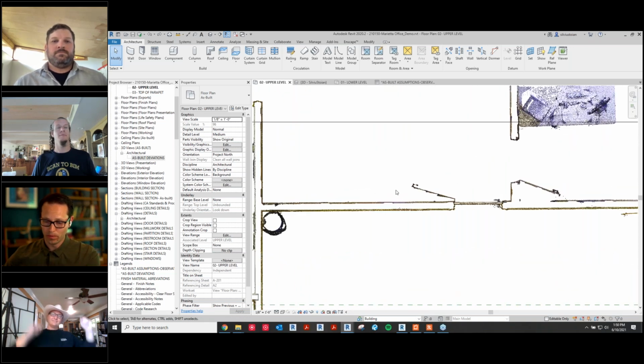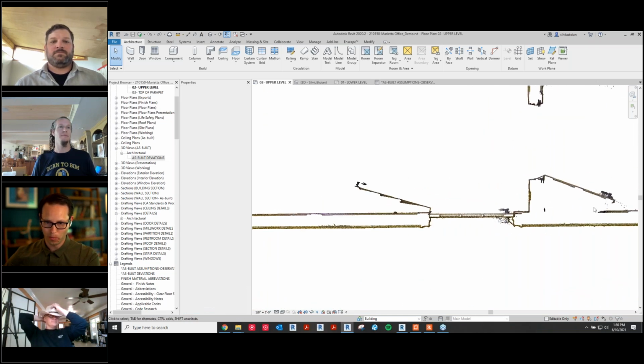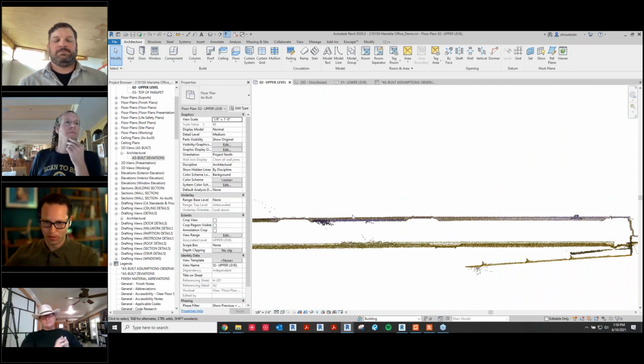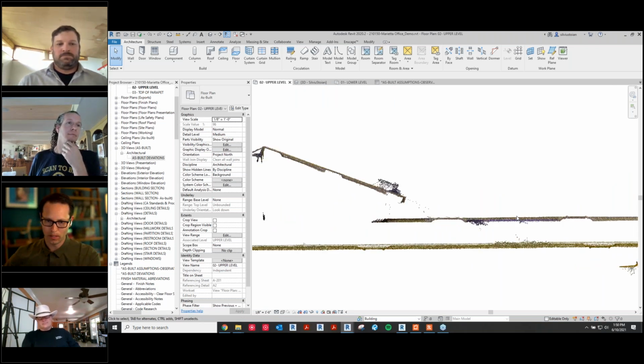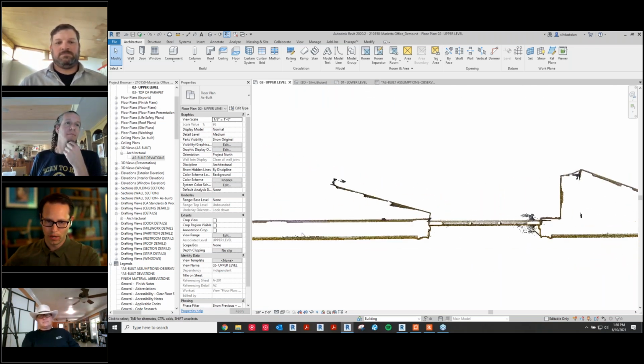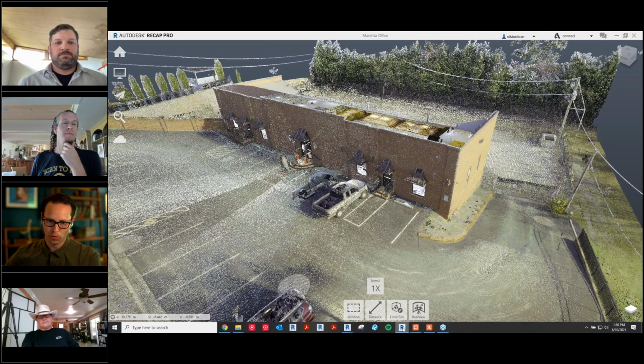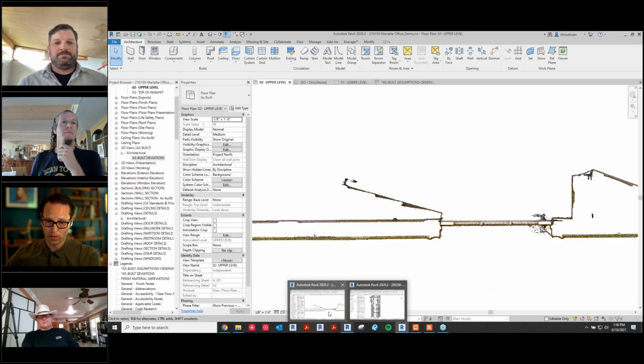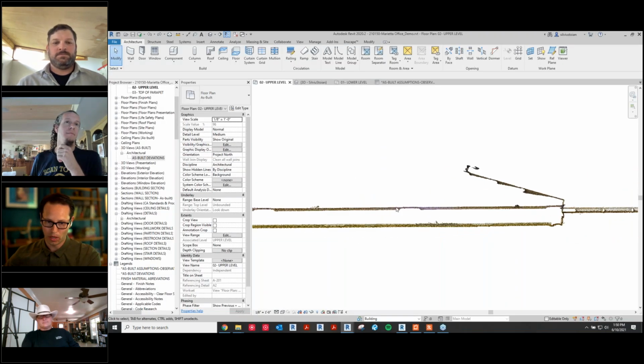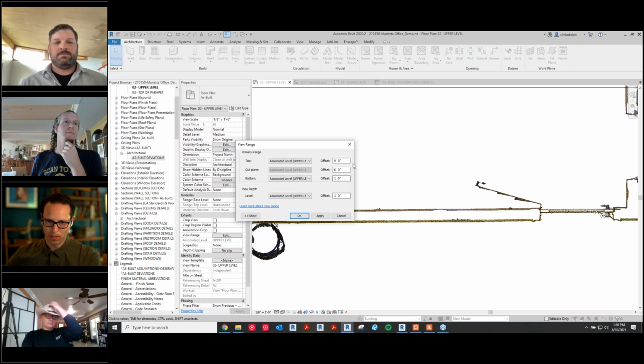So the first step in manual tracing is you look at your floor plan. There's a lot here. There's some paneling on these walls, and you don't know exactly how to model it. Obviously, you need to pair Revit with either 360 views or with ReCap to be able to understand what's inside those rooms. You cannot do one without the other if the point cloud is questionable. But the first thing is to make sure you set your view range to a slice thin enough to eliminate paneling that's lower, or baseboards, things like that.